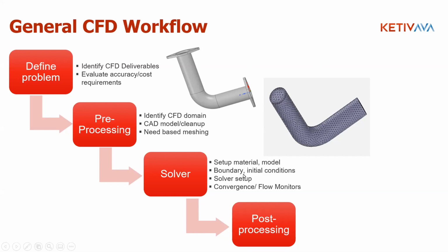The next stage is the solver, of course, depending on which CFD software you're using. You could be using Autodesk CFD, you could be using Ansys CFD. This is the stage where you define the flow conditions and the physics that you want to include in your simulation. Whatever material you want to use, whether it is for the fluid domain or for the solid domain, whatever model you want to use, and by model, I mean, do you want to use a laminar flow or a turbulent flow? Do you want to use a single phase flow or a multi-phase flow? So any of the physics that you want to include, this is the stage where you will set it up.